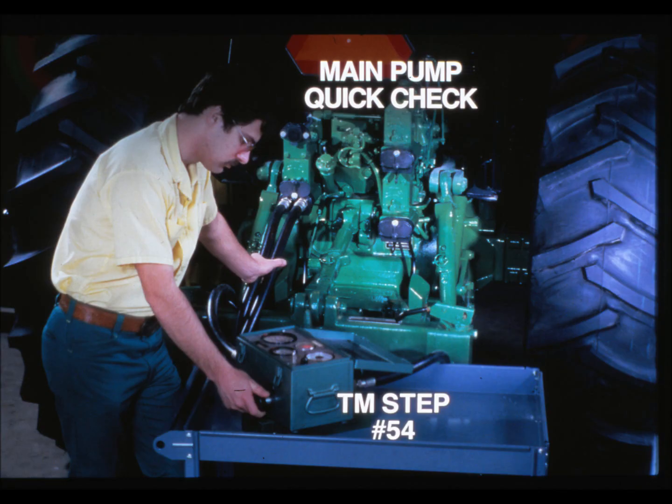Step 54, the main pump quick check, is the last step in the diagnostic procedure. Connect the flow meter across the SCV. Set the SCV metering lever to the maximum flow position. Open the SCV and set the engine at 1,000 RPM. Adjust the restriction setting on the flow meter to get 1,500 psi.